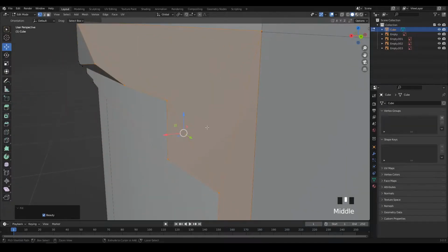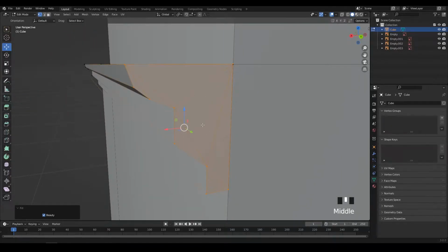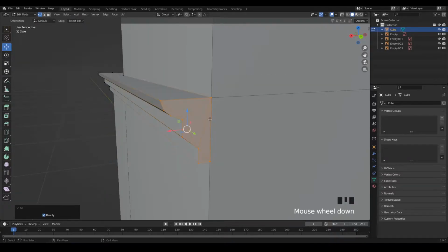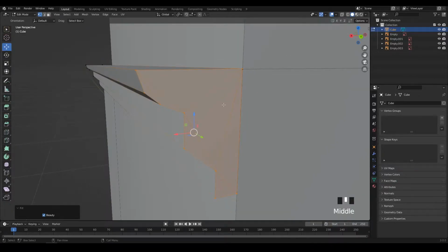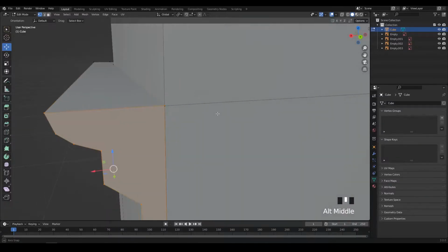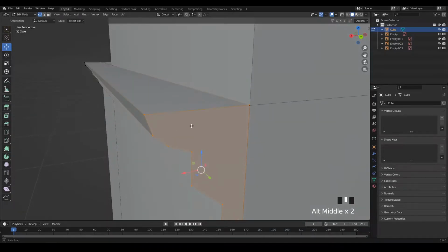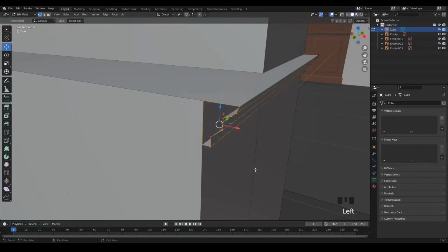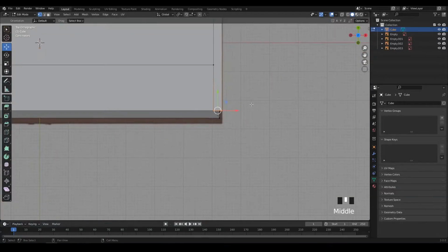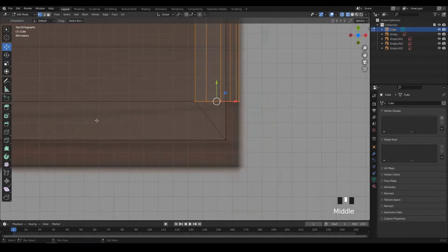This will try to add geometry to it, but because this is supposed to be flat and not change, we could also use the F key on your keyboard as a shortcut for just a normal fill without any geometry. Okay, and from here, what I can do is using my favorite tool now, which is the shear tool.